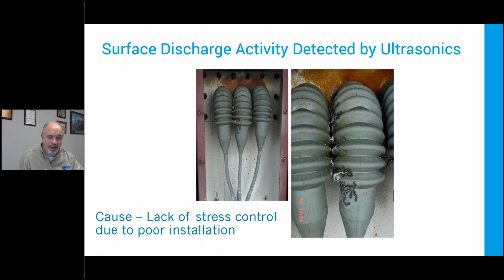And you have a lot of ultrasonic energy. This also created TEV. You can see the rusting on the metal and all the bolts around it. That's from the nitrous oxide buildup and the ozone. So if you go into a cabinet and it's not wet and you've got a lot of rust and your coppers turn green, start to suspect PD.